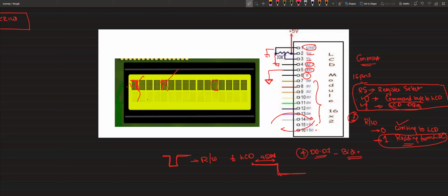So now coming to LCD. We have seen most of the things, except VCC, which is the voltage we supply, and we have a contrast pin to control the contrast of the LCD. The rest are straightforward: ground, VCC, and data, which we have discussed. Now our scope of discussion is, as I said, how to interface it to our LPC2148.